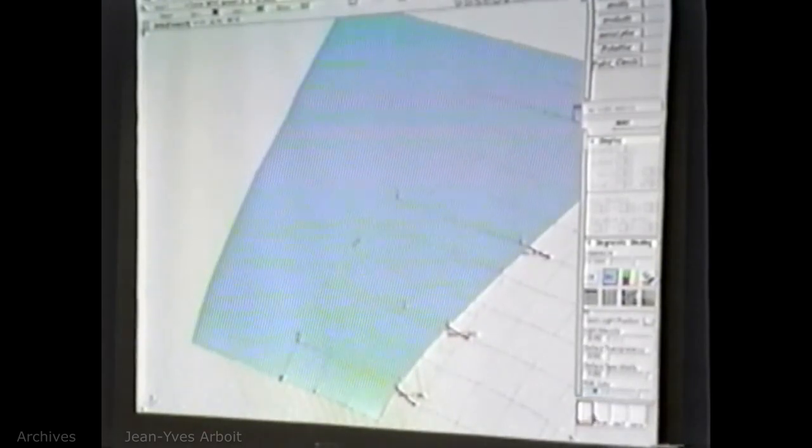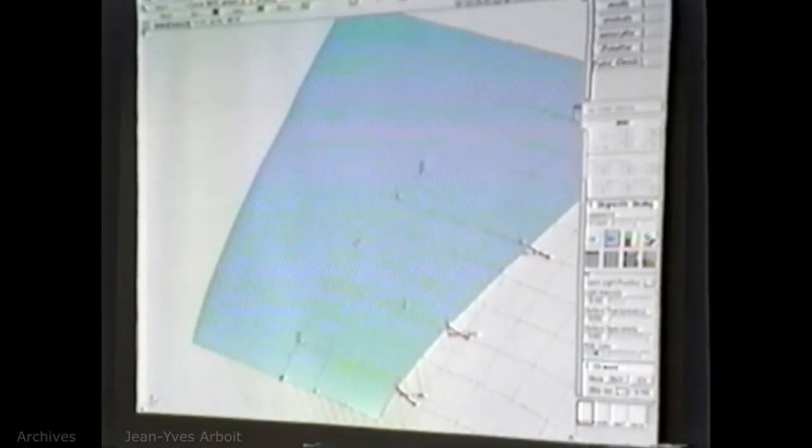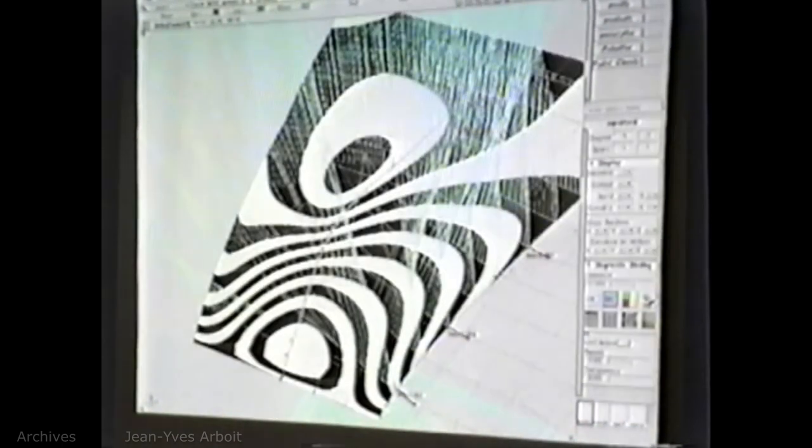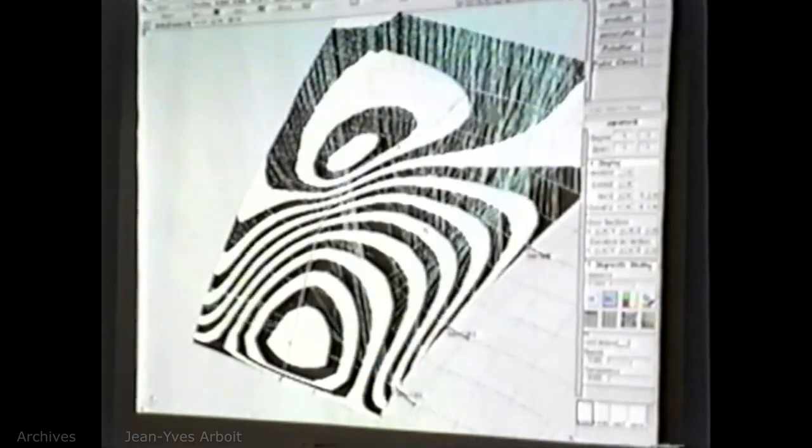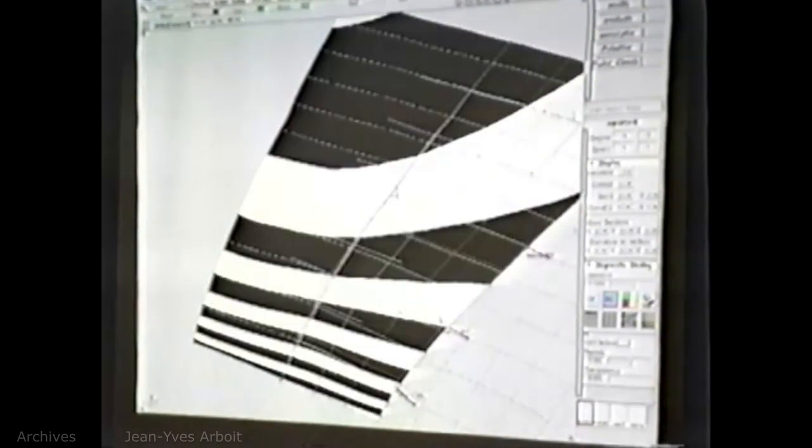To demonstrate, this is a construction history. If I move a CV, let's say XYZ, if I move this one up, whoops, there goes, well, you can see that there are fast updates now. In terms of deviation, I've got curvature comb plots, I put on stripes, you see that, and now I've also got alignment across the center line plane.